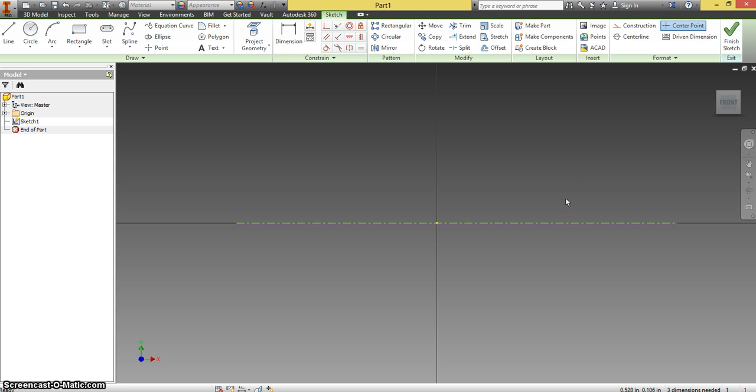So now I'm going to draw what that handle looks like. I guess what I'm going to do is go to the, let's see, top of page 3, and I can kind of get the basic shape around my center line. I'm just going to grab a line. And I like to come up near the origin, and I'm going to draw that basic shape. And I'm going to purposely make it not quite straight, just so I can show us how we can fix that. There it is. That is a closed profile. I've connected one line to another. I'm going to hit escape.